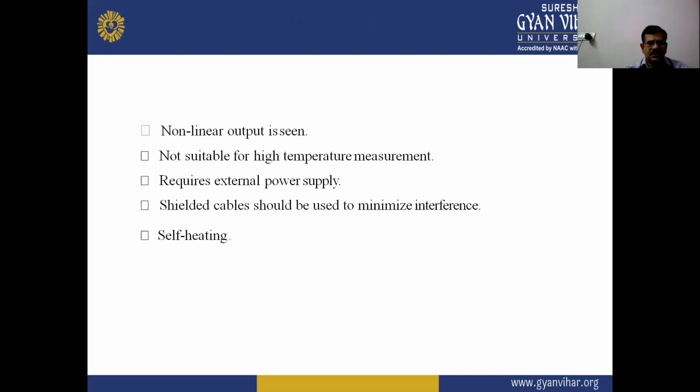And their non-linear output is seen, and they are not suitable for high temperature measurement. So this is a disadvantage of thermistors. And it requires external power supplies. So this is also one disadvantage.